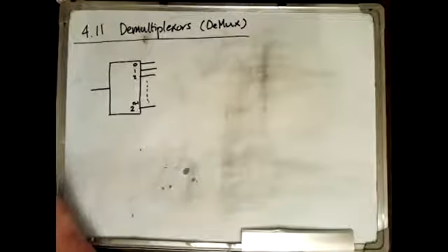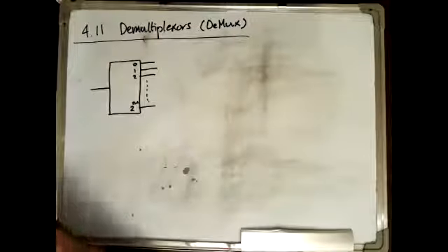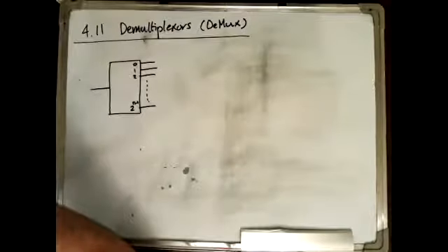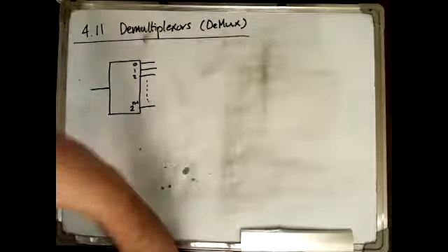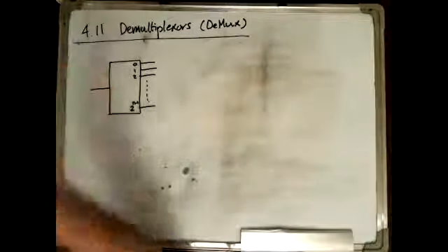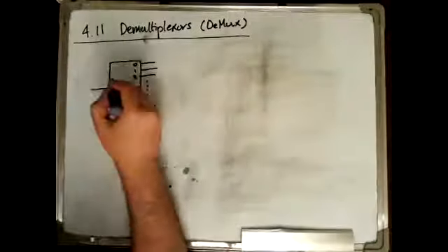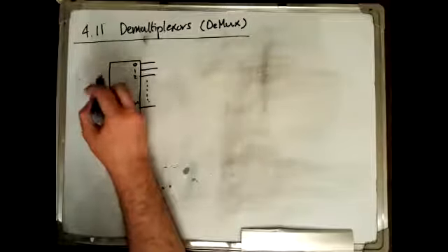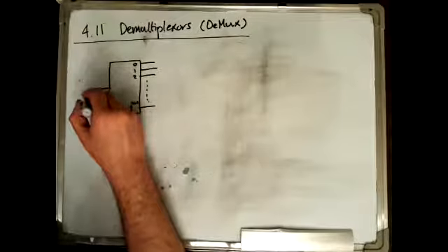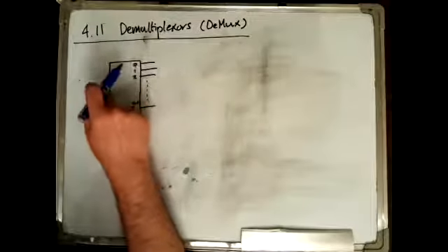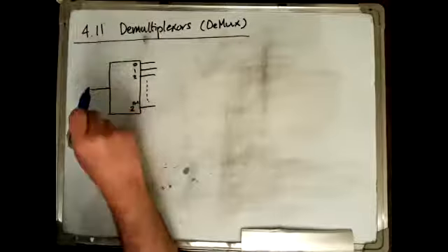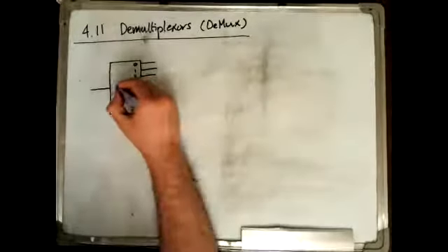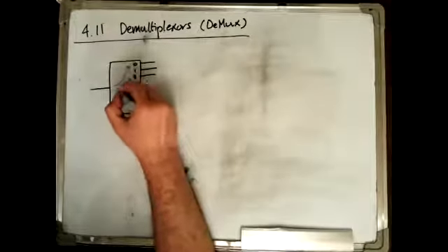And what does this circuit do? What does the multiplexer do? Basically, the multiplexer takes 1 out of 2 to the power n inputs and passes it to the output. What does the Dmux now do? The Dmux takes the value that appears on the single input, there is only one input here, and passes it to one of the outputs.